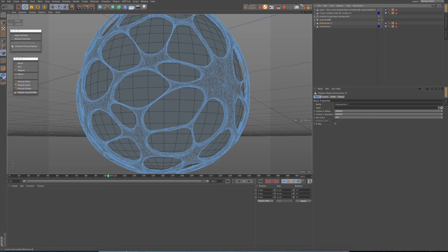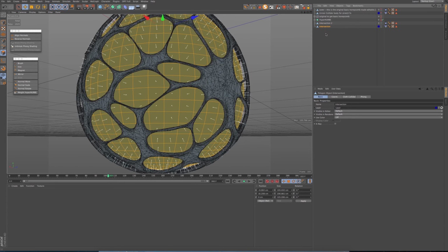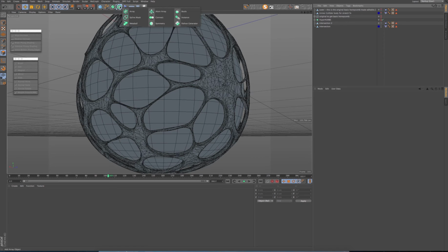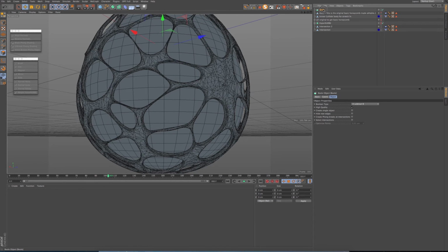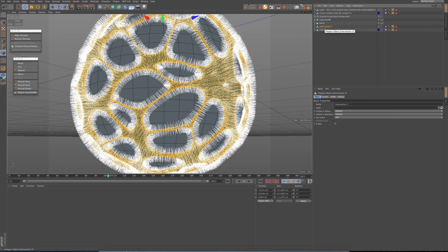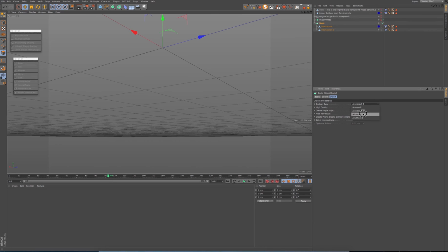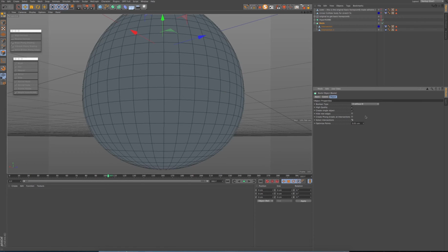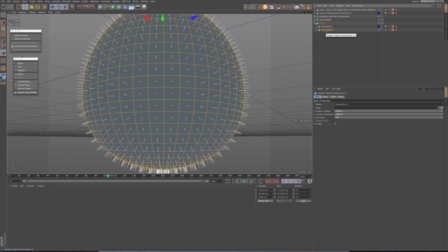So intersection 1, intersection 2, those are the two things that I need to go into my Boolean operator to get the intersections between the two to fill these pools up. So we create a Boolean, and inside that Boolean now we're going to put both of these new meshes that we created. Remember, this is just to fill in the pools. So we now need to change the Boolean operator, A without B, and also we need Select Intersection switched on as well. So the reason why we're not getting anything at the moment is because they don't intersect.